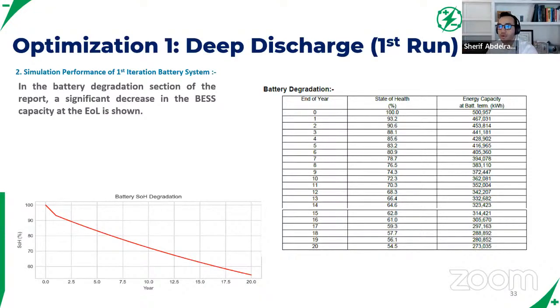So you're really taking a risk there, and you're opening yourself up to operational challenges, balancing challenges between racks and inverters. If you plan to do that, you probably want to account for more downtime and more O&M costs, because it's going to be difficult to manage a system outside of its performance guarantee.